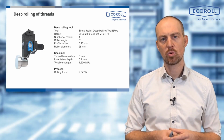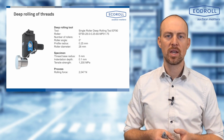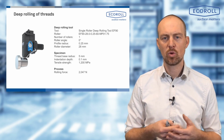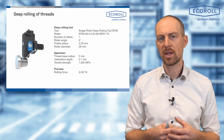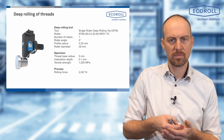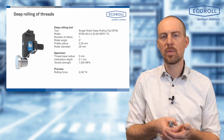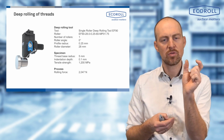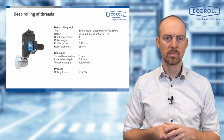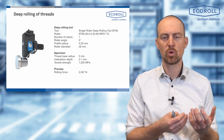This means we have a mechanical tool where a roll, shaped to be suitable for the thread, is pressed into the thread root and then guided along the thread. A specific rolling force, in our case 2 kN, was applied. And then we reinforce the thread again at the thread root. The thread roll is now designed to fit exactly in the thread root. It is mounted in a floating manner, meaning it can shift slightly and finds itself exactly in the center of the thread root. This has an advantage in terms of process reliability and ease of execution for the worker.